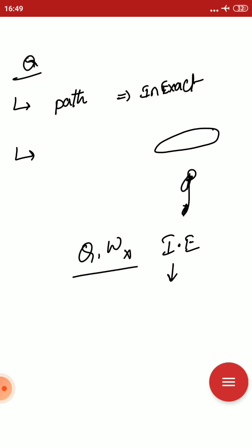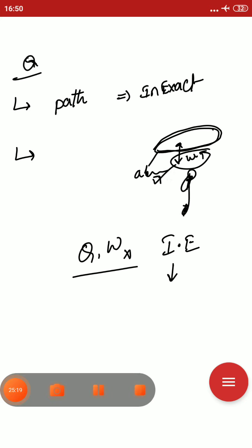An adiabatic process is one in which there is only work interaction between the system and the surroundings. In the adiabatic process, when the system is covered by an adiabatic boundary, energy transfer takes place only by which type of energy transfer, as I told you? Only work transfer, because the boundary does not allow heat flow, so the only way energy transfers is by work.